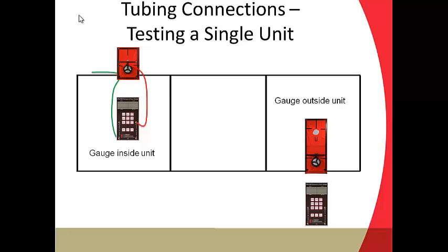Let's say you're testing a 3-unit building and you set up with the gauges outside. You could, with one person, do this test. You could set each one up to cruise, enter the baseline in each gauge, set each one up to cruise 50, let them settle out for a bit, push long-term average on each gauge and write down the numbers.